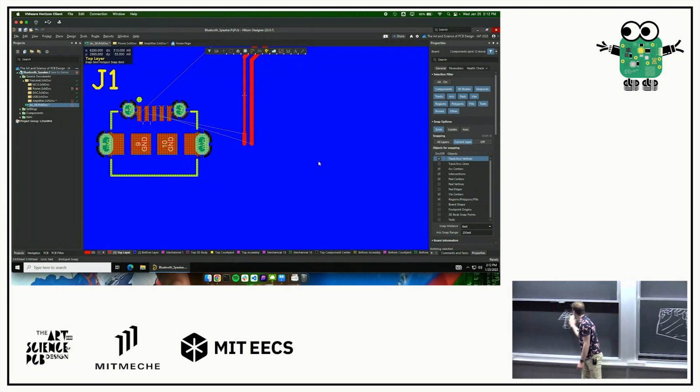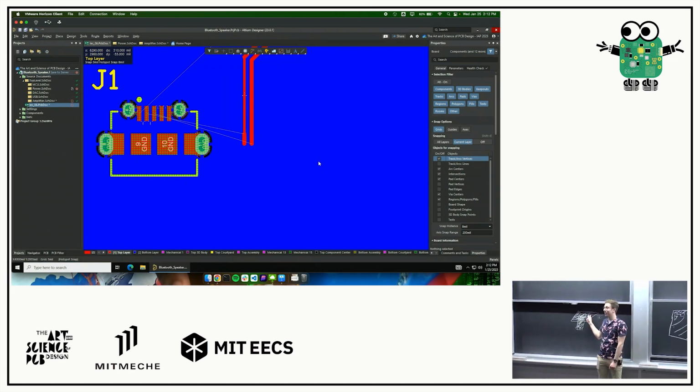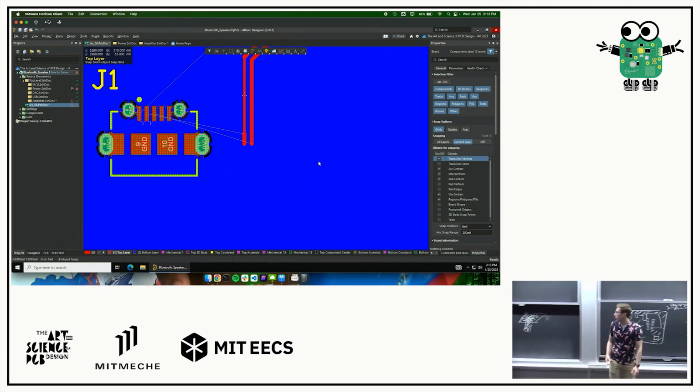This whole thing is going to get plugged up with solder, right? So is there going to be any left on the pad? No, not really. There's going to be a little bit, depending on how much went in the hole and whatnot. But it's all going to go in here. There's not going to be a ton on here. And then now our part isn't as secure as we would have wanted it to be otherwise.